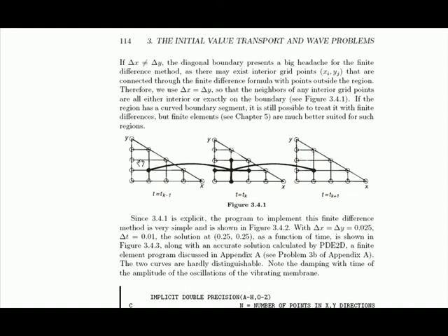So if we have complicated regions, you should normally use the finite element method. Finite difference method is easy to use if the region is a rectangle, or here this is not a rectangle, but it's still pretty easy to use, but you have to be careful that the grid points lie on the boundary, otherwise it complicates things. So we'll normally just use finite difference methods in rectangles or real simple regions. For more complicated regions, we need to use the finite element method.